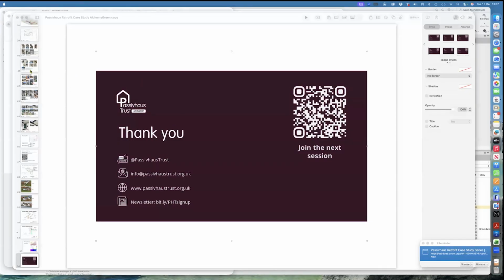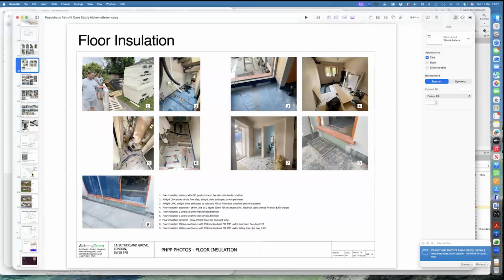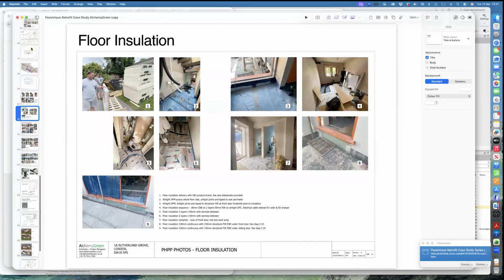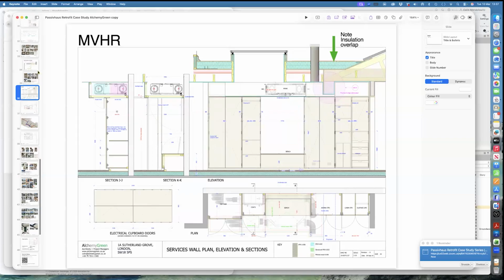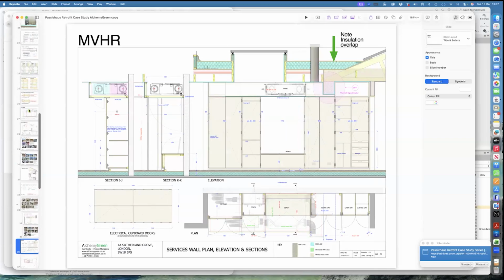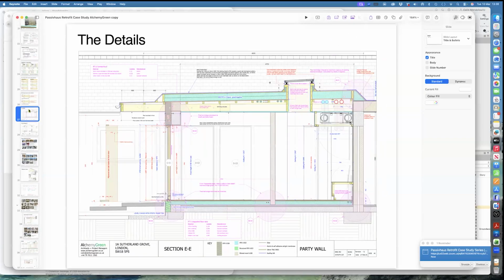The thermal bridge had black mold in the bedroom corners, and because it hadn't been lived in for a while, the building was actually quite musty. So you knew you had a thermal bridging problem there with those big concrete beams, and that covering those was going to be a big win in terms of having continuous insulation, and that would sort out a lot of your problems.